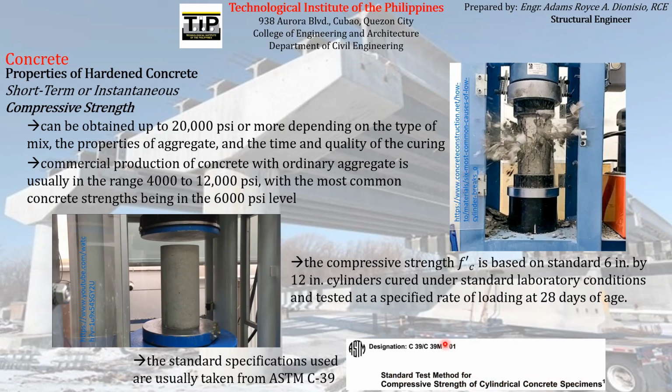So actually you have to familiarize yourselves with these ASTM standards, ASTM C39, because if you will be conducting a thesis or capstone design which is related to concrete, most of the time you will refer to this standard, the ASTM specification for conducting the standard test method for compressive strength of concrete cylinders.